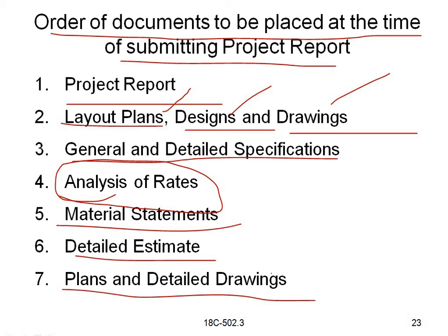Regarding the plans we have to prepare the drawings also, like the footing plan and column plan: the size of the column, the size and depth of the footing, the column height, and where the slab is. These should be drawn comfortably and prepared. By that we exhibit all quantities of items and detailed estimates.